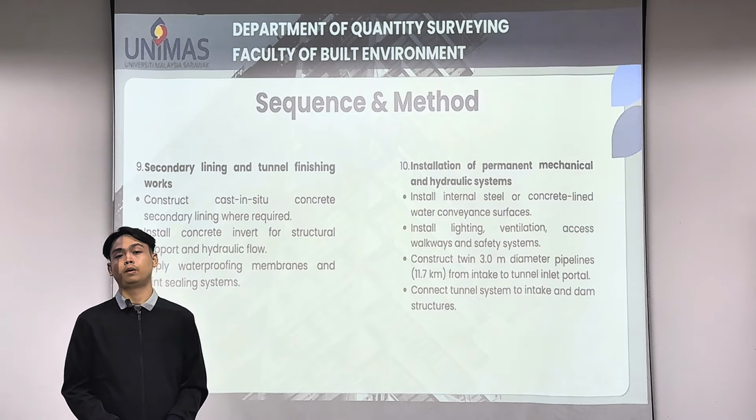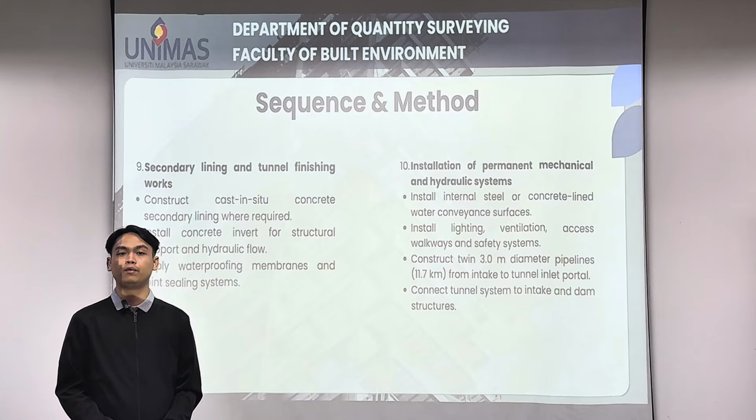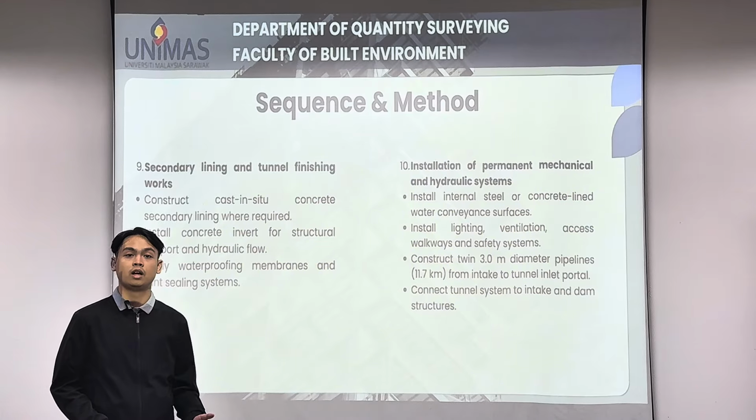After excavation and primary support, secondary lining and finishing are done. Cast in situ concrete and a concrete invert provide structural strength and smooth water flow, while waterproofing and joint sealing prevent leakage, ensuring a durable tunnel ready for operation.